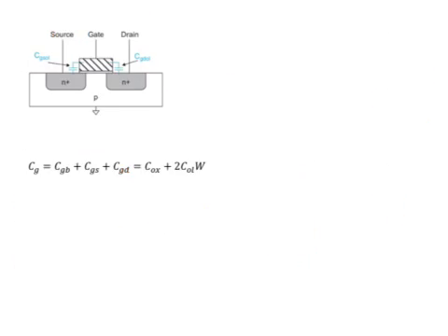One more factor to note when you think about the composition of the gate capacitance in modern processors: typically the gate tends to overlap to a small extent with the drain and source regions, creating an additional overlap capacitance, and this overlap capacitance also contributes to the gate capacitance.